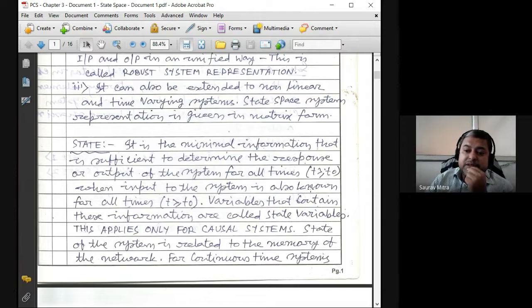Okay, so initial time is 0. And after that, at any instant, so at t is equal to 0.1, 0.2, 0.3, 0.4, if you are taking the time intervals very small, in that case, the number of states will be more. So if I tell you that iL(t) is equal to e raised to minus 3t, just to give an example. The current flowing through the RLC circuit, that is iL(t), is equal to e raised to minus 3t, because it's a decreasing kind of current. Now I ask you, tell me the current after every 0.1 second. So how many states will be there between 0 to 1? There will be 10 states or 11 states.